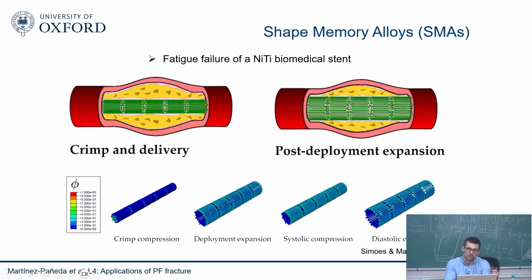We also solve a variety of boundary value problems, and you can find details in the paper. One of the applications where nitinol and shape memory alloys are most widely used is biomedical stents, because you want to crimp them first, compress them initially, and then expand them quite significantly. But you don't want irreversible deformations, and you also want a lot of elastic cyclic loading, so you want some sort of elastic hysteresis. This is basically to ensure blood flow. Sometimes blood vessels can be blocked, and you unblock them through these stents.